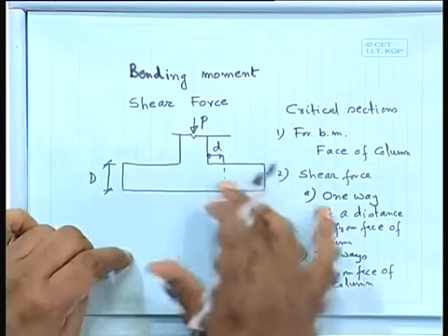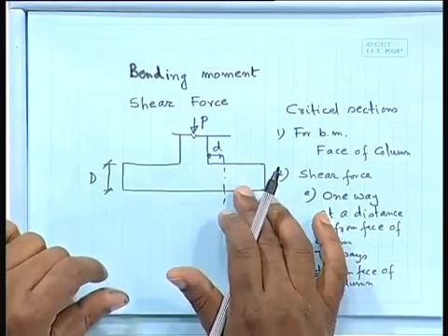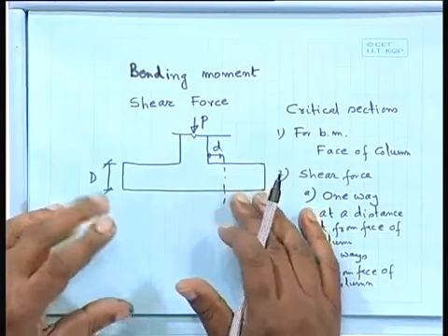But generally in this type of footing, we do not provide any shear reinforcement. There is no provision for that. We could do it, but we don't want to do it here. So the only alternative you have is to increase the depth, so that the shear stress developed is less than 0.35 Newton per square millimeter.